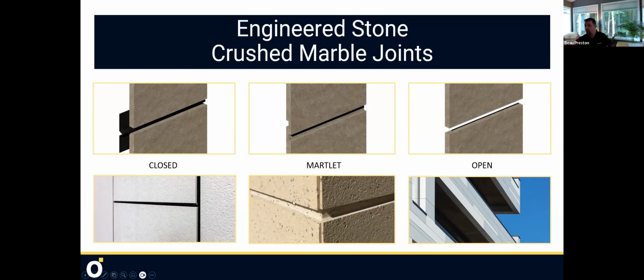Or we can do traditional open joint, which I think is the highest and best use of an open joint rain screen, because you get the best equalization of pressure in the wall. We can still mitigate those with the other ones, but easiest is to keep an open joint, but we can do all of that. Most will just say, hey, we're an open joint rain screen, have open joints.